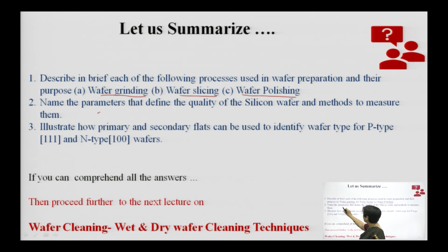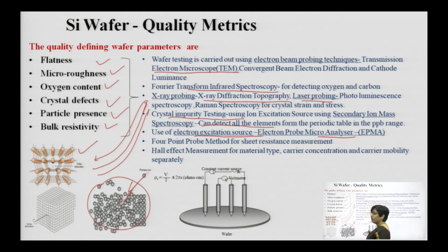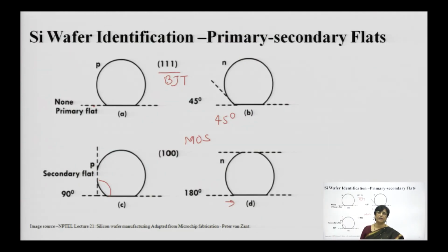Then, can you find parameters such as micro roughness, substrate properties, and sheet resistance, like we have seen. The sheet resistance is also very important. In the previous slide I showed you that you are using 4 probes. Between 2 probes you have a constant current and across the other two we measure voltage, and you know the properties and the distance between them. So, sheet resistance can be calculated from the 4-point probe method. These are the different techniques for identifying the electrical characteristics.